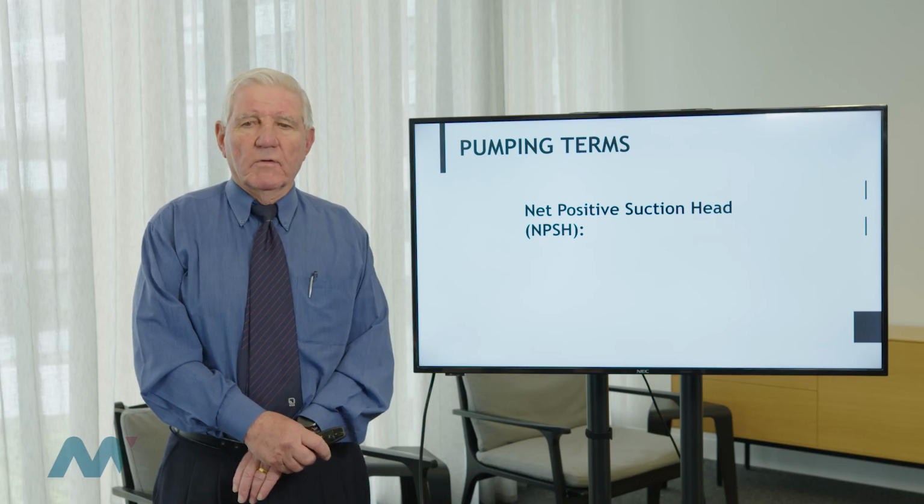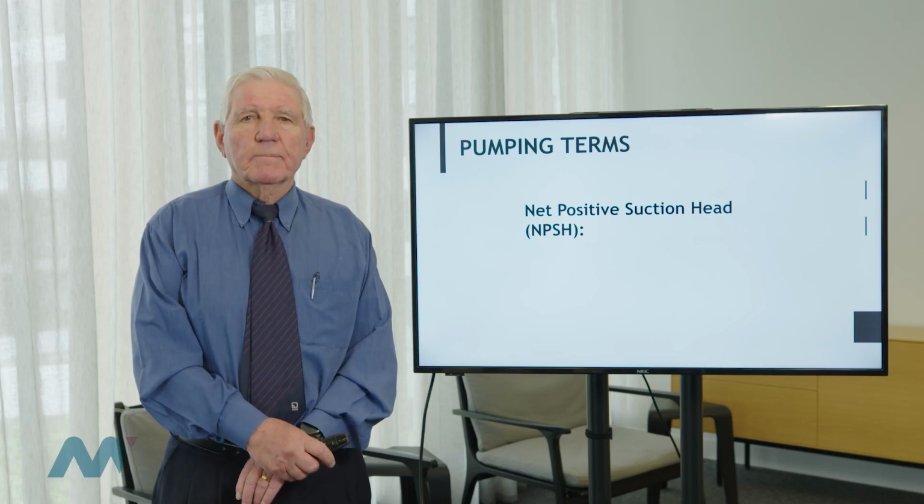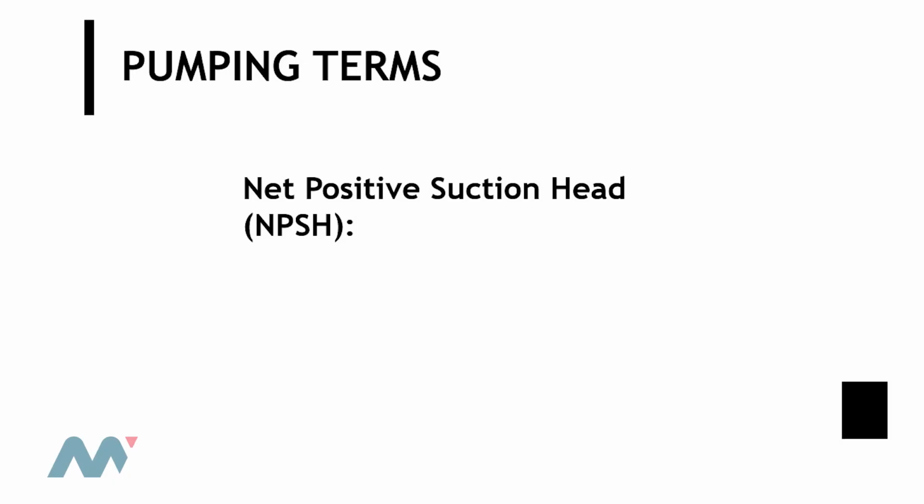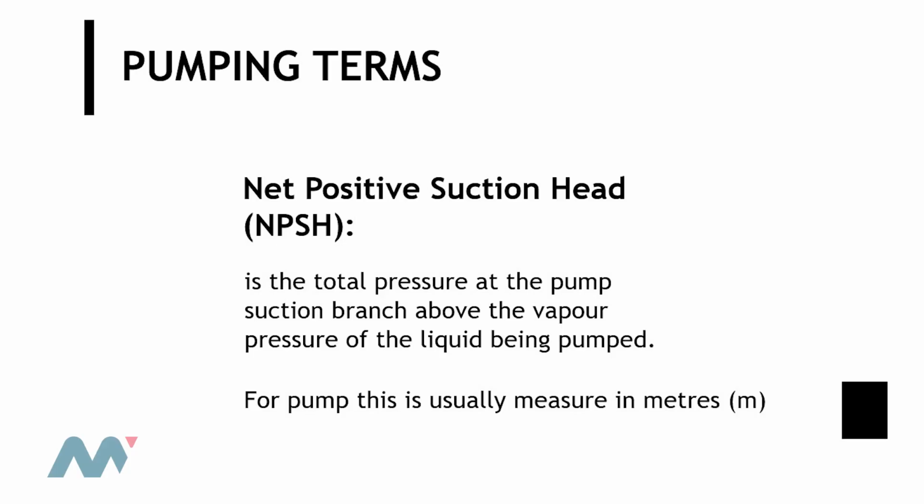So NPSH and cavitation is the topic that we're dealing with, and we've got to understand what NPSH stands for. It stands for net positive suction head, and that is basically the pressure that is applied at the pump suction. The NPSH actually consists of two components.